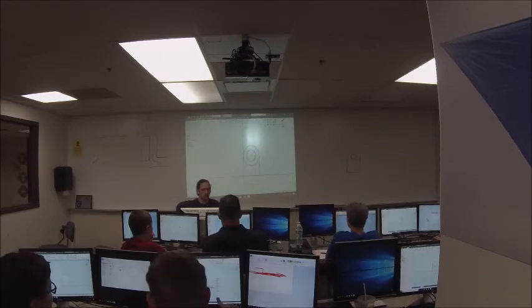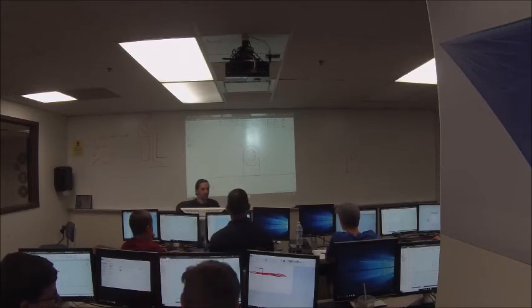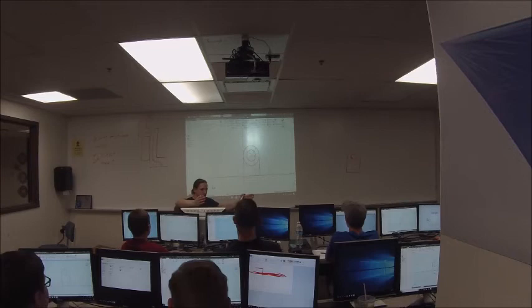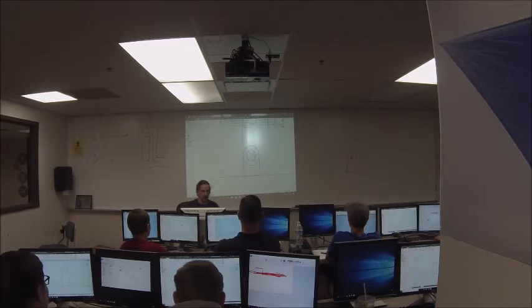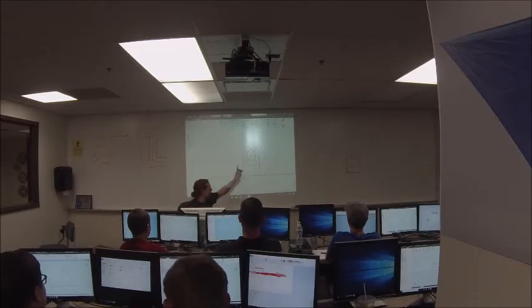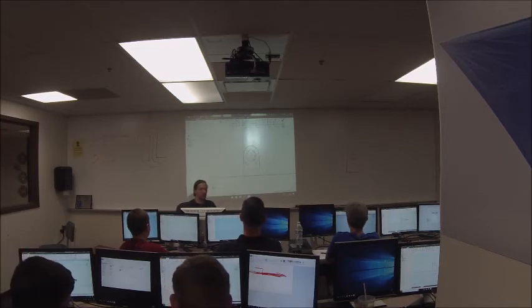It's up here. Okay, so the trim tool basically removes pieces of lines and shapes that are between other things, right? So I can click here and I could remove, you can see how this hovers over, it's a dotted line, I could remove that piece and it cuts the top off but leaves the bottom part of the circle. I'm going to undo that. But what I want to do is click the trim tool and click the bottom half and it trims the bottom off.